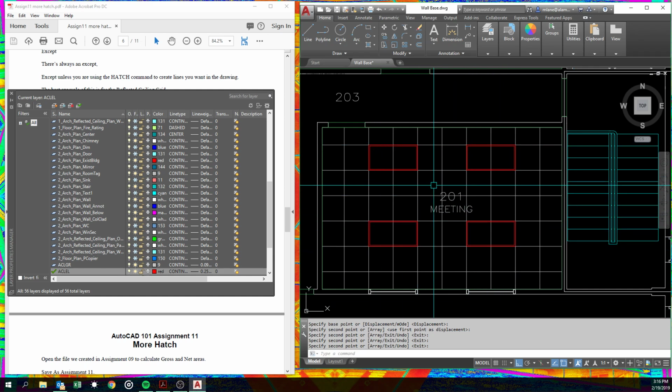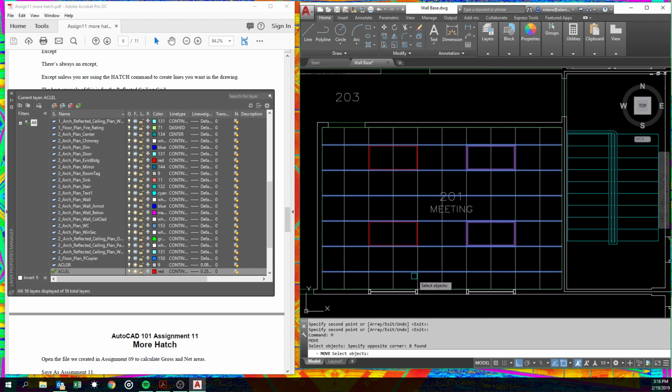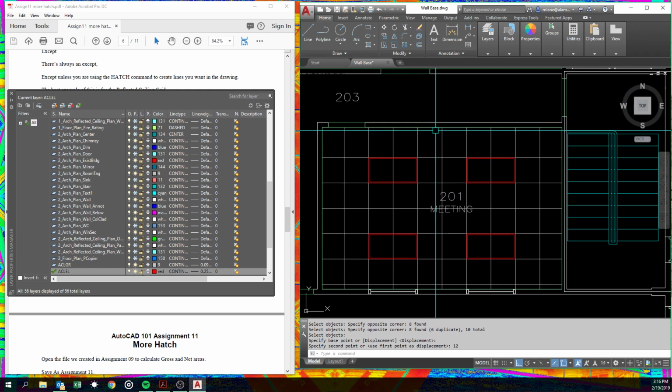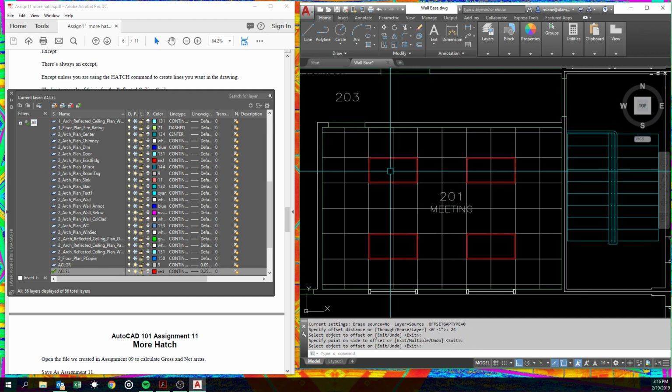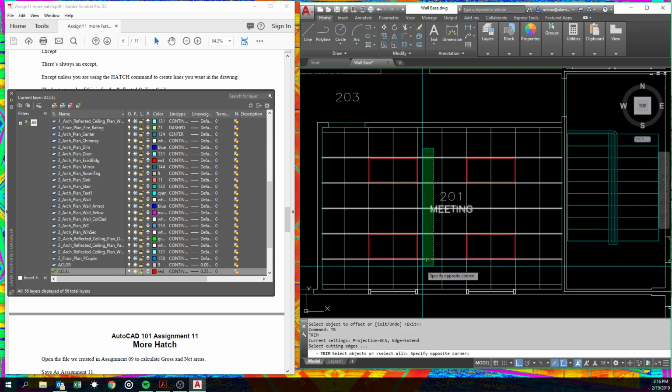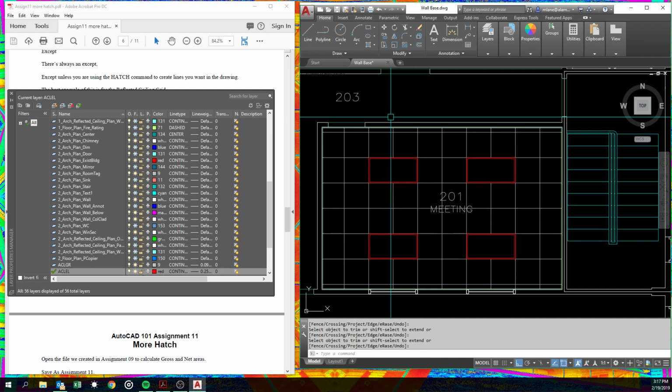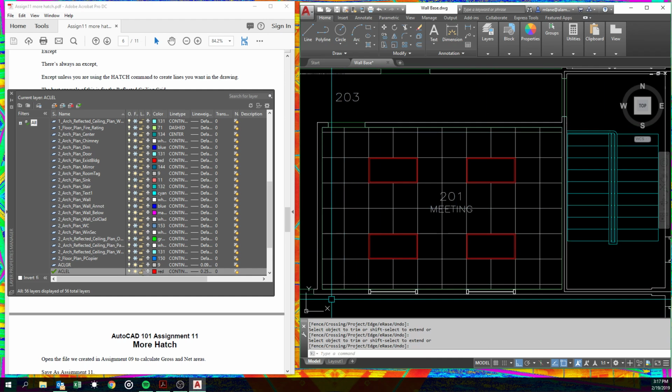That table's going to be in the center of the room. Oh, no. So we're going to have to move these lines. Even though we moved them because we didn't want skinny edges, we're going to have skinny edges in this room. So we move it back down 12 inches. Now we have to offset 24 to put another grid line in. And we need to trim this little bit in here out, so trim. We'll pick all these lines because it doesn't matter if we pick extra ones. And then we get rid of the parts we need. And that's our ceiling layout.